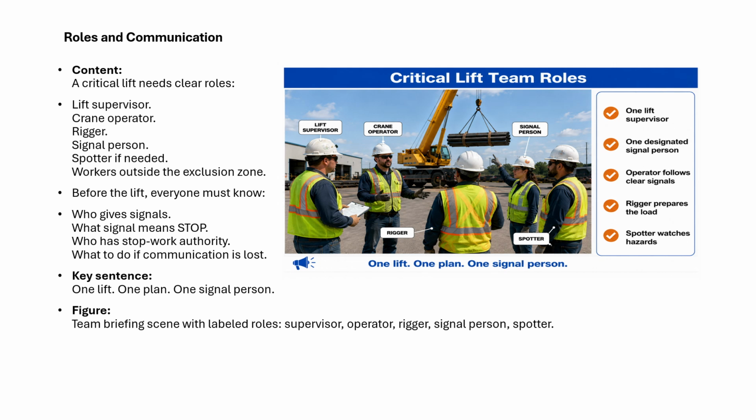Roles and communication. A critical lift needs clear roles: lift supervisor, crane operator, riggers, signal person, spotter if needed, and workers outside the exclusion zone.